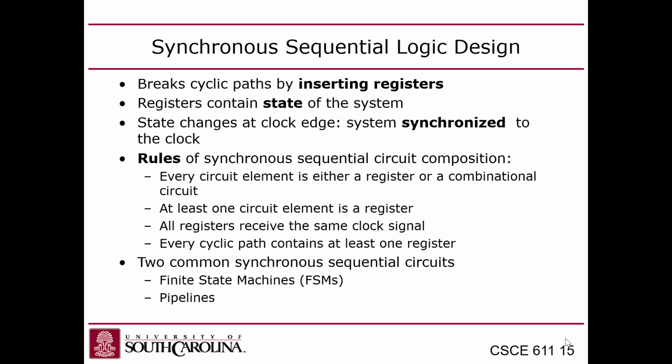Okay, so how do you design synchronous circuits? Well, there's sort of a formal and an informal way to do it. As I mentioned earlier, we've already designed synchronous circuits in this class by putting in shifters and counters and that kind of stuff. Another way to do it is to build a synchronous circuit as a finite state machine, as a design that explicitly shows states and transitions between states.